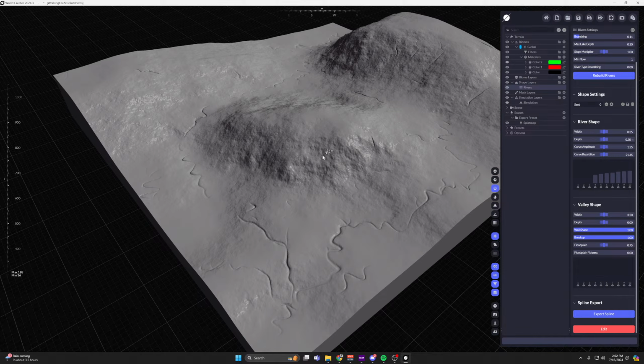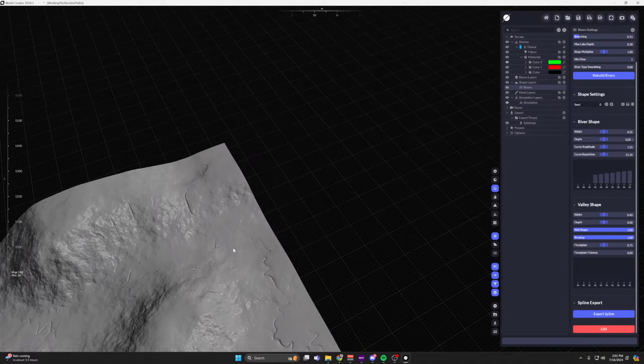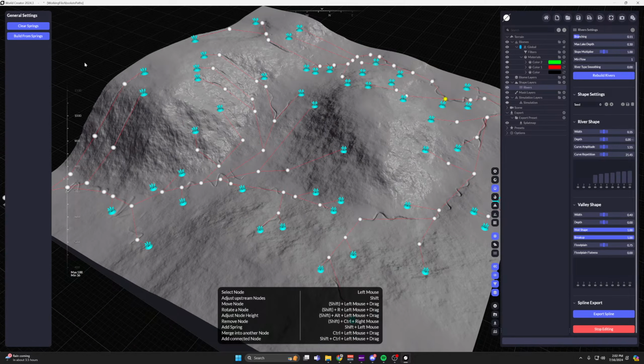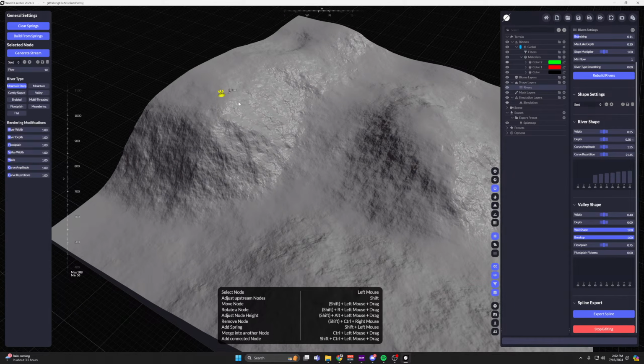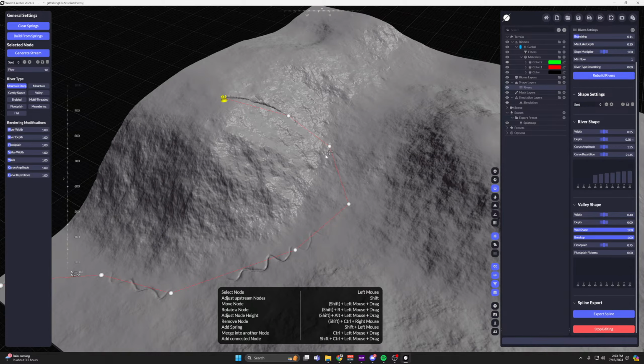Especially if you want to add rivers to an existing height map, it's best to remove the valley altogether, have valley do nothing, and have the river be what's going to guide everything. So what I like to do is come through here, clear the springs. I like to create my own springs. So shift click. And with this particular stream selected, generate stream, and you can see what they do one at a time.